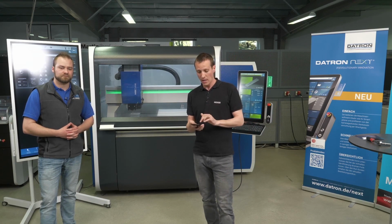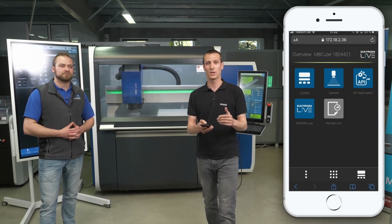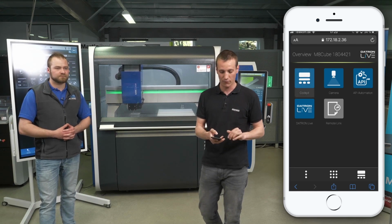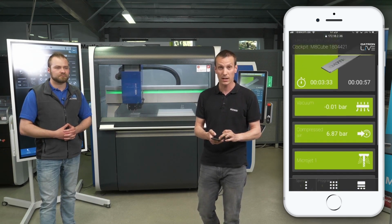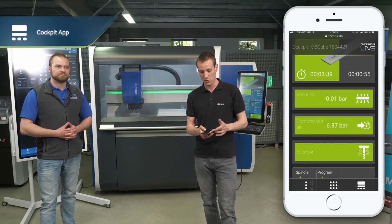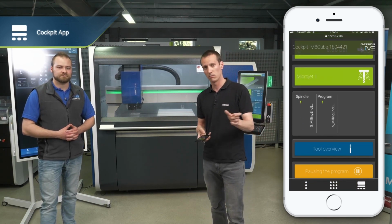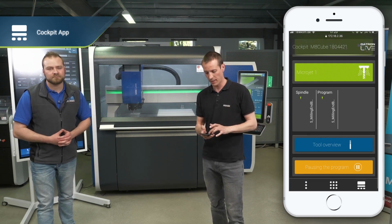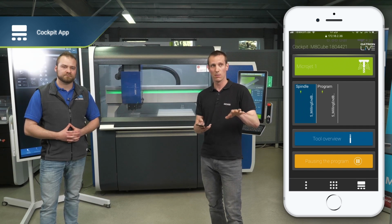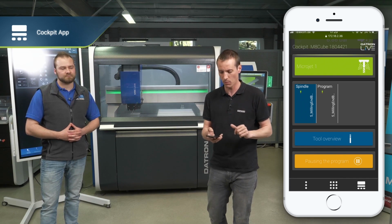What I have in my hand now, what you can see now, is an app that has the connection to the machine. So I'm logged into this machine right now. I have a cockpit that tells me exactly what's going on with my machine. I get information about the remaining time, about vacuum, compressed air. I can look into my tool data, if tool life is expiring and so on. And I can pause the program, which you can see down there, this orange button. You can just pause it if there is something strange.